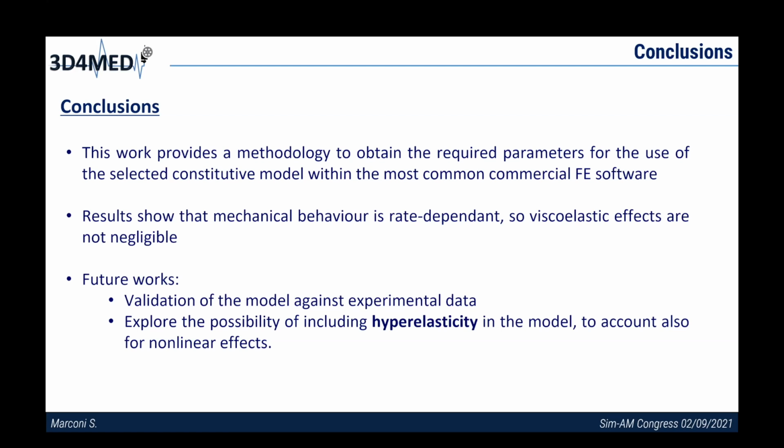Thank you. Mr. Shanmugam Kumar, please. Yeah, thanks, Stefania, for the nice talk. But I was wondering whether the Vero White is also exhibiting kind of viscoelastic behavior, because it exhibits yielding, hardening, and softening. So if you were to combine Vero White with some elastomer or rubbery polymer, something like Tango Plus, and if you combine Tango Plus in very small quantity, do you still expect this kind of material response?